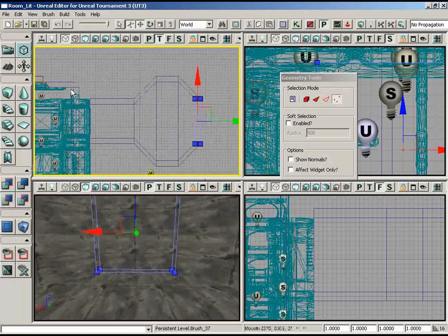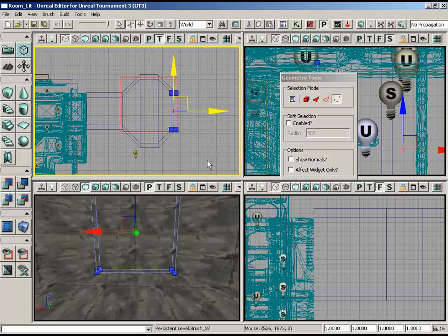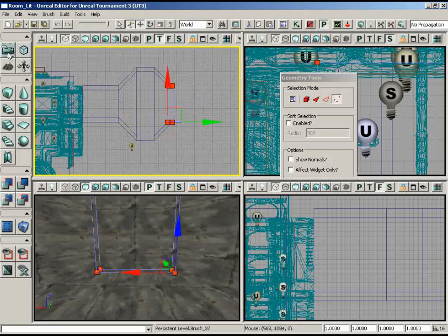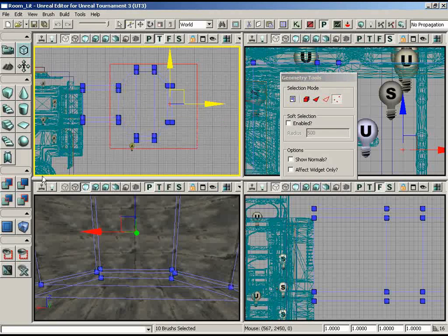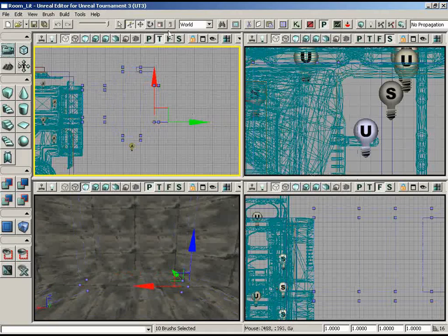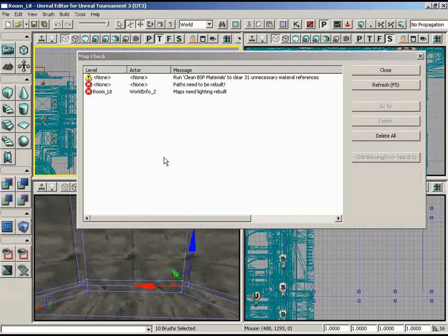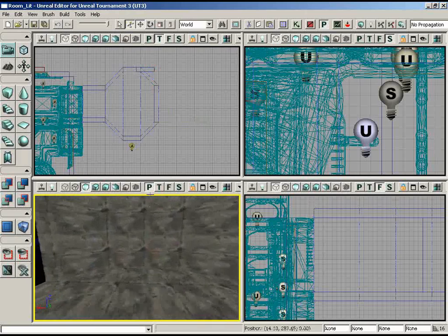I mean, we could vertex edit everything and just slide it back in some. If we wanted less of a corridor, we could take all of these brushes, not in geometry mode, then switch to geometry mode, grab all of their vertices, and maybe drag them in, and give less of an open corridor. So I mean, that might give a more immediate look.